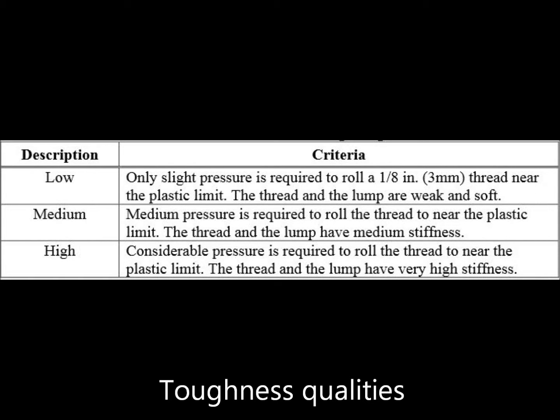Toughness. In analysis of toughness, we also use our observations from the plasticity test. If it took notable pressure to continue to roll the soil as it approached its plastic limit, we can say that the soil has a high toughness, more characteristic of clays. If the soil remained weak or soft, it was likely more silty.